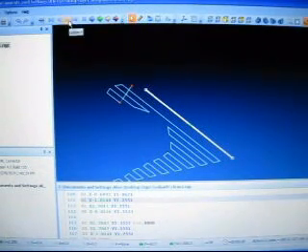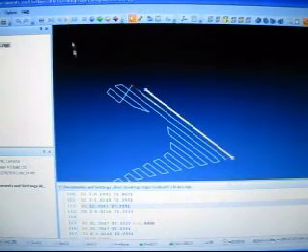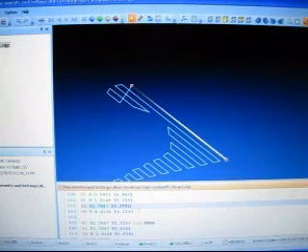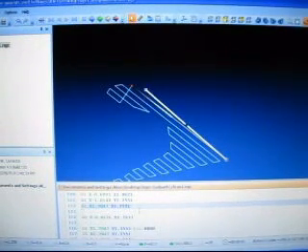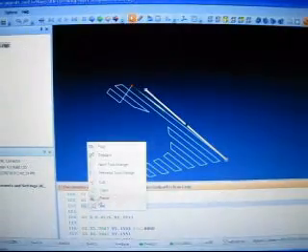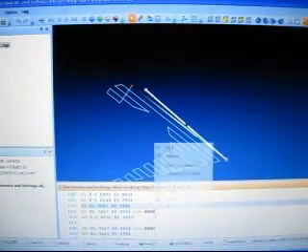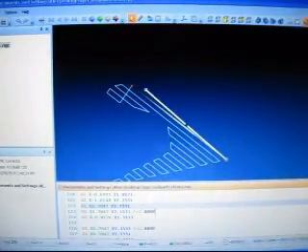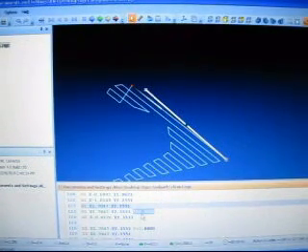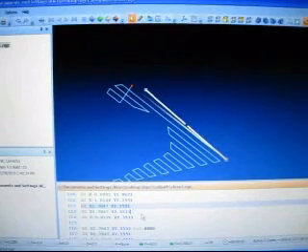So it's going to have to be right after this line. Okay, I'm going to enter a space, boom, and I'm going to paste that code. And now I'm going to eliminate the feed rate. We don't need it. We don't need the feed information.